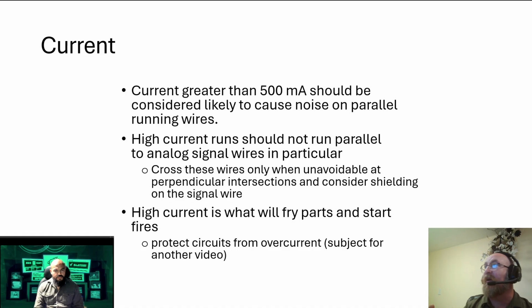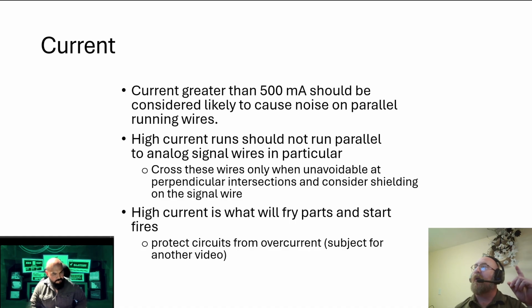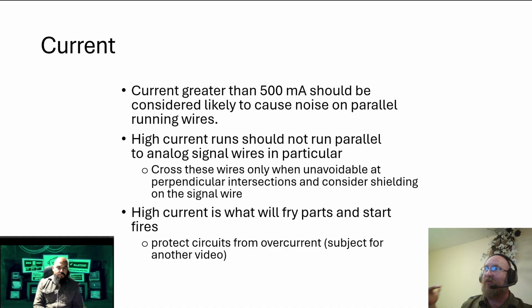On the power side of things, anything that's high current will fry things. We've got to be aware of that. And it's not necessarily the voltage you're worried about when it comes to stopping your heart. It's more the current. It is a balance though. Voltage is what allows it to penetrate through the skin and tissue to reach your heart. But once it reaches your heart, it's the current that kills you, and the current that burns you. It's the current that causes all of the bad effects of a shock. Until you reach a high enough voltage to penetrate the skin, none of that matters, because you're not really completing the circuit until it can make it across that resistance.